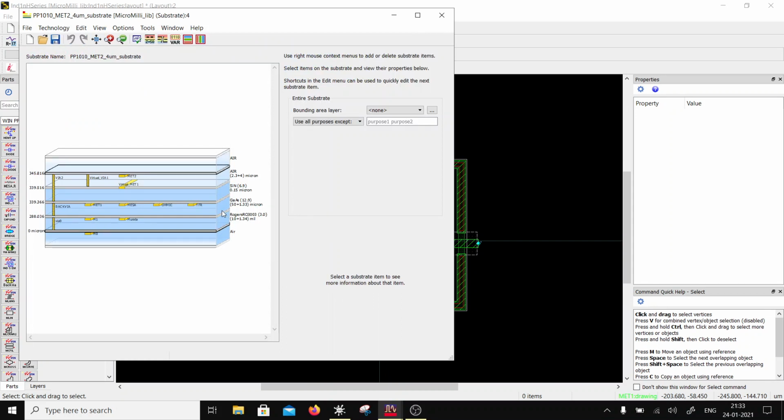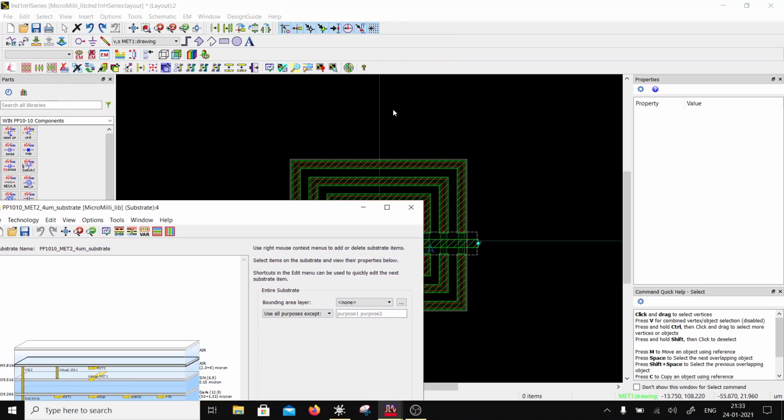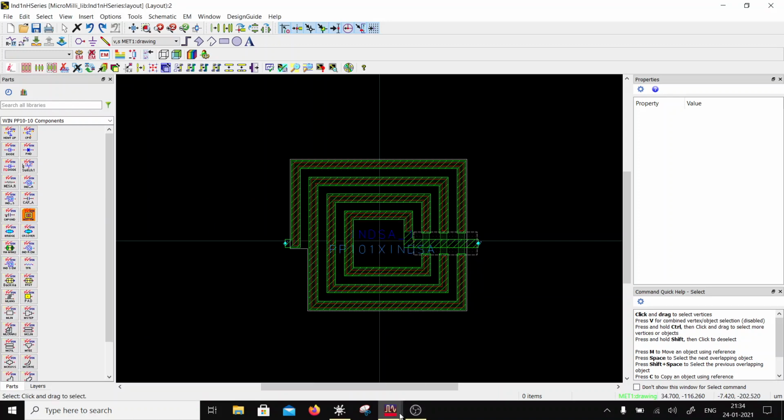Okay, so we have 50 micron of gallium arsenide. Now the question is whether you want to keep everything coplanar on the layout. At high frequency it is preferable to keep everything coplanar, right? Or whether you want to do everything microstrip, then impedance control on the chip is difficult, right?